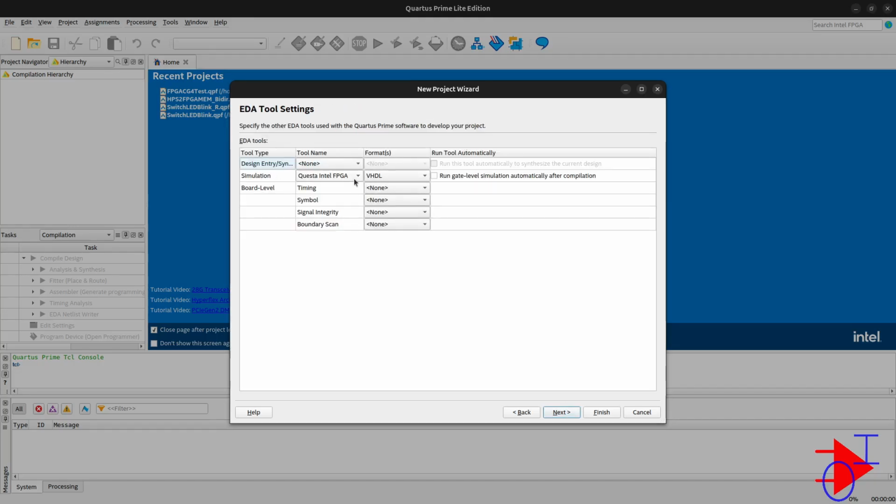Next, I don't want to simulate my code. Basically, once you build, this option helps you visualize at least, I believe, 100 nanoseconds or 10 milliseconds, something like that. It will give you the pulse output of the selective signals from the program, and you can figure out where the error is happening. So that's the simulation. I don't want to use that right now. Just want to continue, build a simple program.